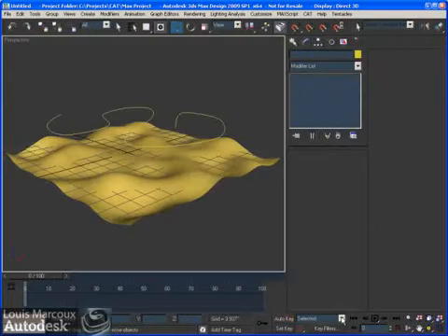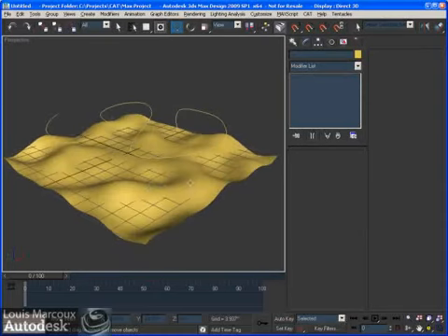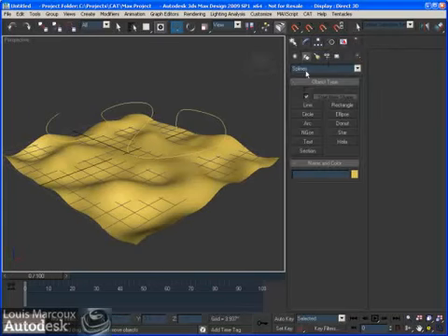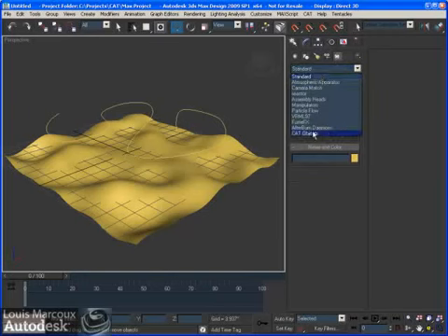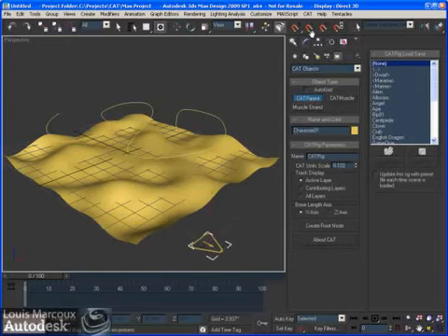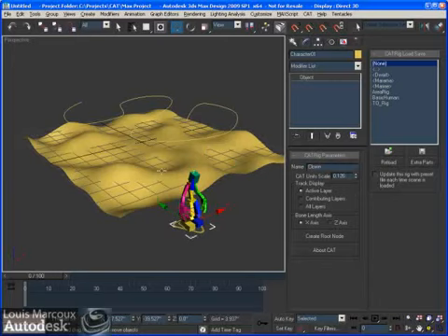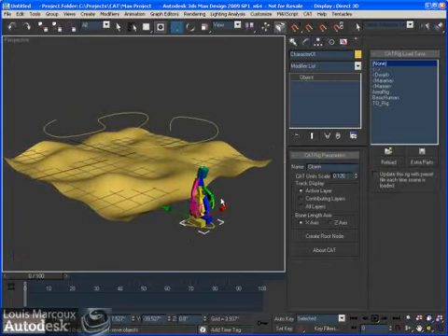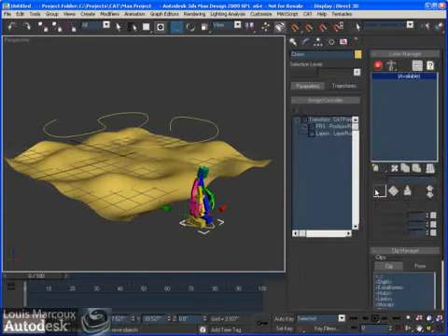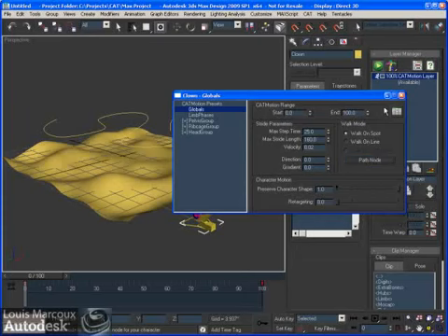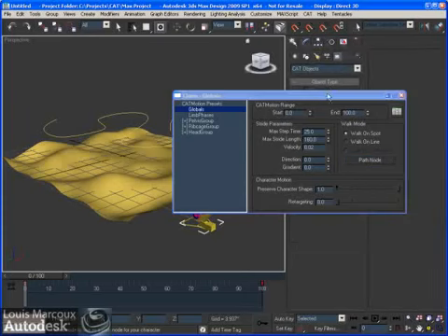Okay, I got distracted a little bit when I was doing the feet adjustment, so I forgot to mention one important thing about cat motion. Let's go back here, and I'll just create my cat object again, and create a cat parent, and we'll just use the clown to start with, like so. And it's a bit big, so I'm going to reduce the size here compared to my overall scene. So now we've got our cat layer, our cat rig. So I'm going to add a cat motion, go into walk cycle mode, go into the cat here, and I'm going to go into the globals and say path node, and I don't have a path node yet, so I'm just going to go back and create.